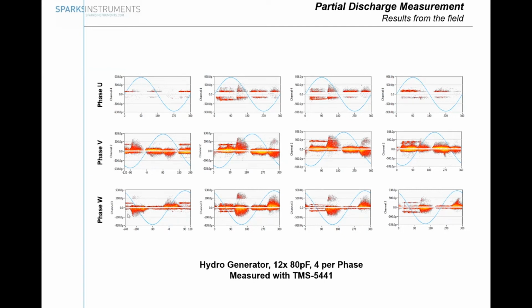Let's say, for example, this type of discharge. Okay, here the discharge is present, same phase. Here still a little bit present. Here fully disappeared. The same here on the top. Okay, that looks like the discharges are somehow in between these two sensors. But the sensor on the very left side of the winding or the very right side of the winding can't see that at all, or just very tiny. So it can be beneficial for some types of machines.